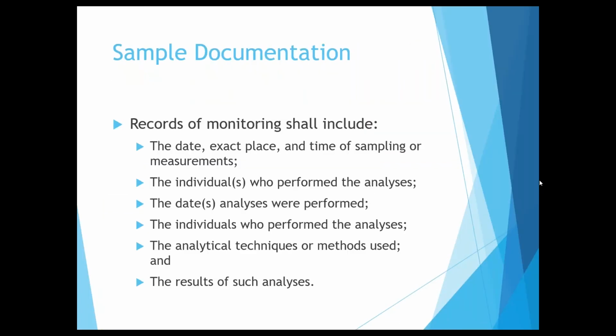Okay, yes. If I could ask, kind of related to what you were just talking about, Jeffrey Rollins has asked a question. If your permit requires a 4-hour composite, could you instead collect a 24-hour composite for A, better representation, and B, meeting the hold time before the lab can pick it up? I would not. I would follow what the permit says. Talk to your permit writer to see what they recommend you do.